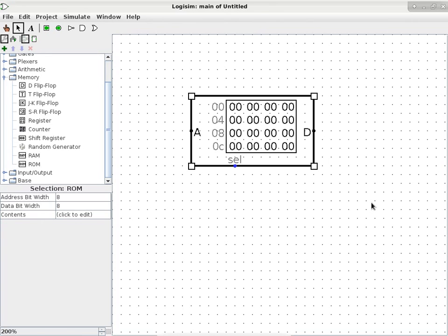If you hover your pointer over these ports, it will explain what each is. It says it's the address bus, the location accessed in memory. In other words, this interface tells the ROM chip which location you want to access, because somebody else wants to access the memory, and this is how you tell the ROM chip, hey, I want to access location 56. Once location 56 is addressed, it needs a way to tell whoever is inquiring, oh, location 56 has a content of, let's say, 7D.